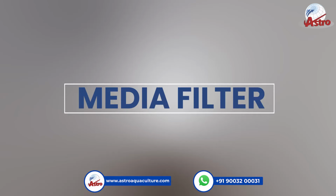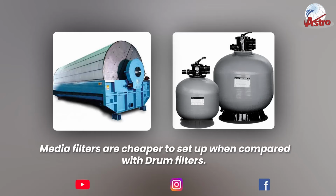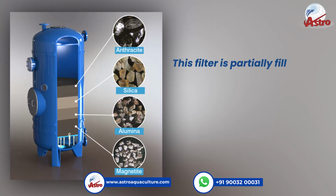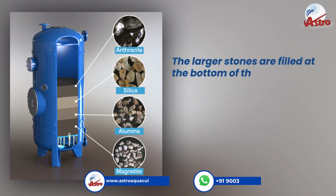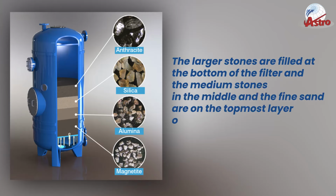Media filter. Media filters are cheaper to set up when compared with drum filters. This filter is also known as sand filter. This filter is partially filled with gravel, stone chips, biochar and sand. The larger stones are filled at the bottom of the filter and the medium stones in the middle and the fine sand are on the topmost layer of the filter.